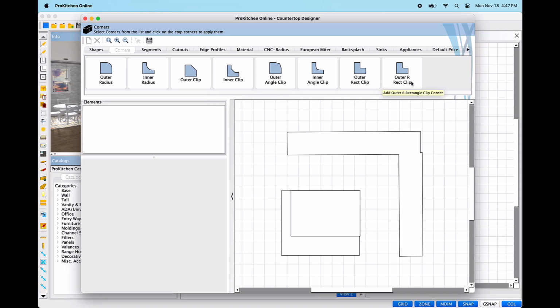Once a corner shape is selected, the left panel will activate and allow you to adjust the corner radius for curved corners, delta points for beveled and angled clips, or width and depth for rectangular corner clips before placing into your design. Again, either by highlighting the current measurement and typing in the required value, or by utilizing the arrows to the right.